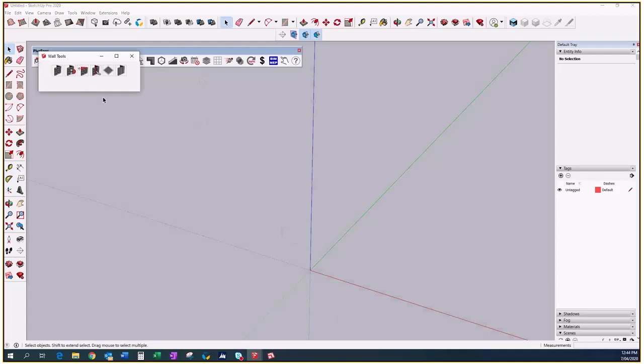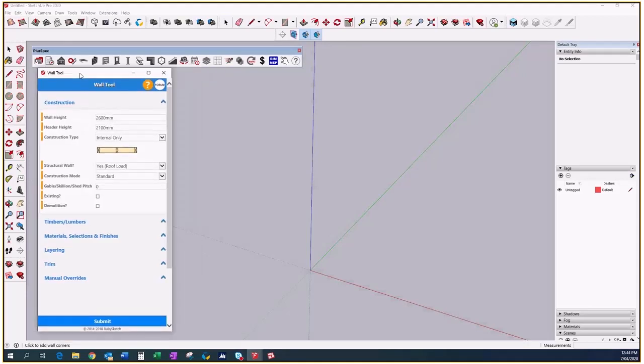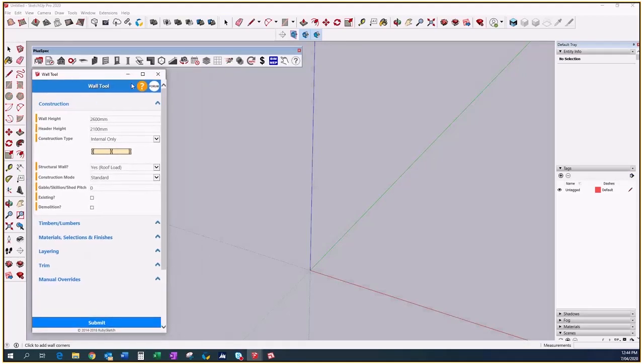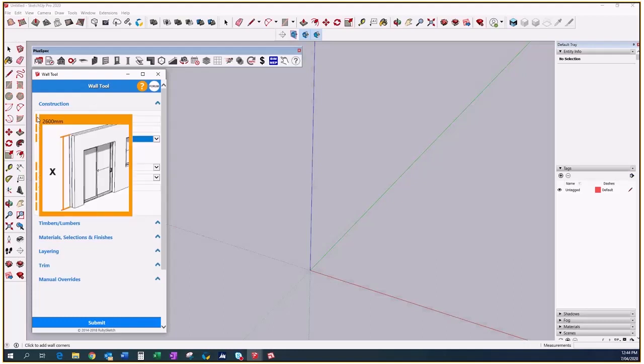Because like traditional tools, like Revit, ArchiCAD, whatever, it is allowing you to draw with actual building products. So if you want to draw a wall, you're going to draw a wall. It brings up, I'll just bring it over here, attributes. So you're going to be able to attribute this wall. So what do I want it to be? Masonry veneer, blah, blah, blah. So I might do a masonry veneer. Again, you can put your wall heights, header heights.